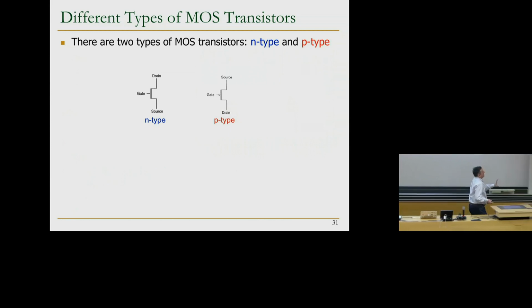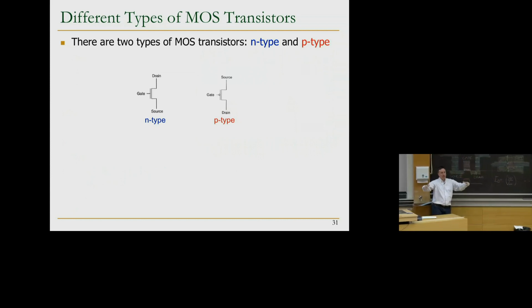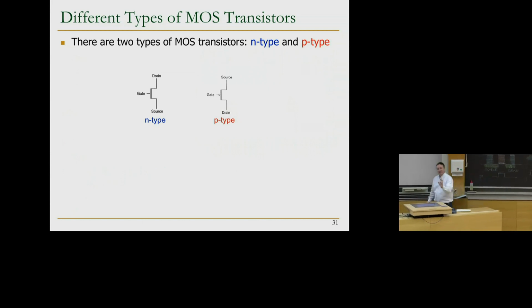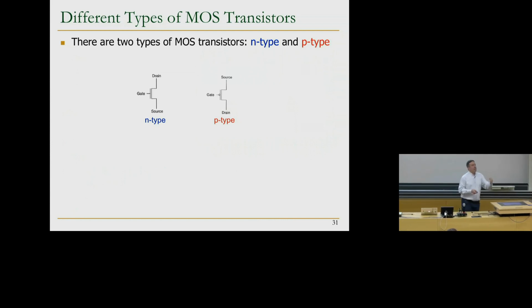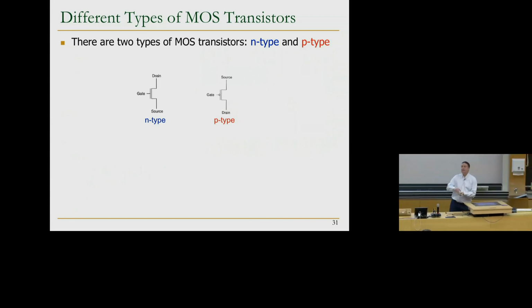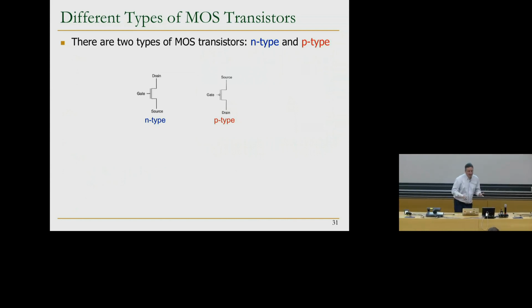And notice that I was talking about semiconductors being cool. You can engineer these regions. You can have your big chip, and any part of it you can say, let me make this N. Let me make this region P. I can define a small region and say, this 5 micrometers by 2 micrometers will be of type N, meaning that I am building an NMOS there. Or you say, this region I will make P, and I will make a PMOS there, which doesn't sound very exciting until we see that they are actually useful.